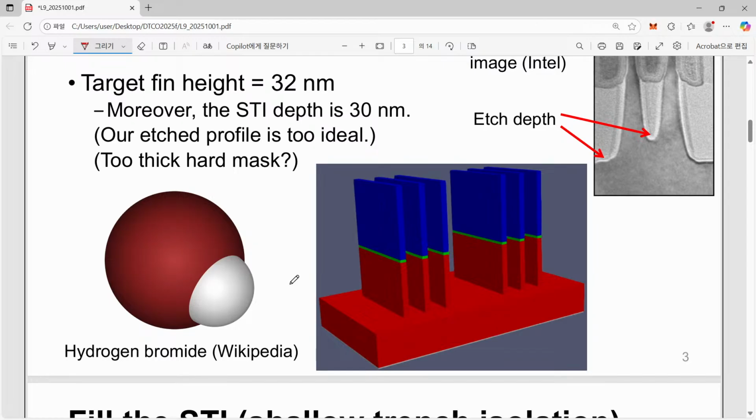Yes. First of all, thank you for your question. This deep substrate is intentionally set to be just 1 nanometer because it is never etched and nothing happens in the deep substrate. And I intentionally set the thickness of the silicon as 99 nanometer.